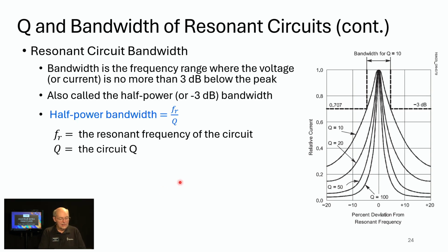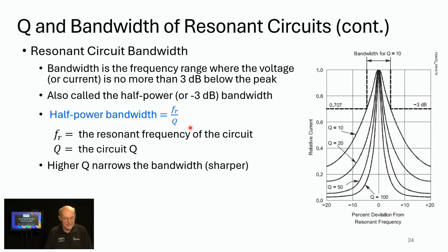And here's the formula. This, I hope, doesn't look difficult if you're scribbling things down on that sheet of formula reference paper that we showed earlier. You can write this on your paper. Half power bandwidth is the frequency of resonance divided by Q. There's a couple of questions in the pool that actually ask you to calculate this, and they're extremely easy. It's just the frequency divided by the Q, and they give us both of those.